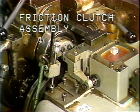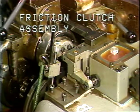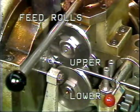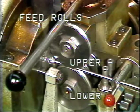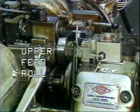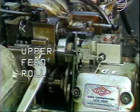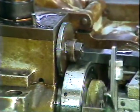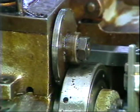When the friction clutch is engaged, movement of the stock feed attachment is transferred to the upper and lower stock feed rolls. Mounted on the back of the upper feed roll shaft is the friction disc. The purpose of the friction disc is to provide rotation to the upper feed roll.